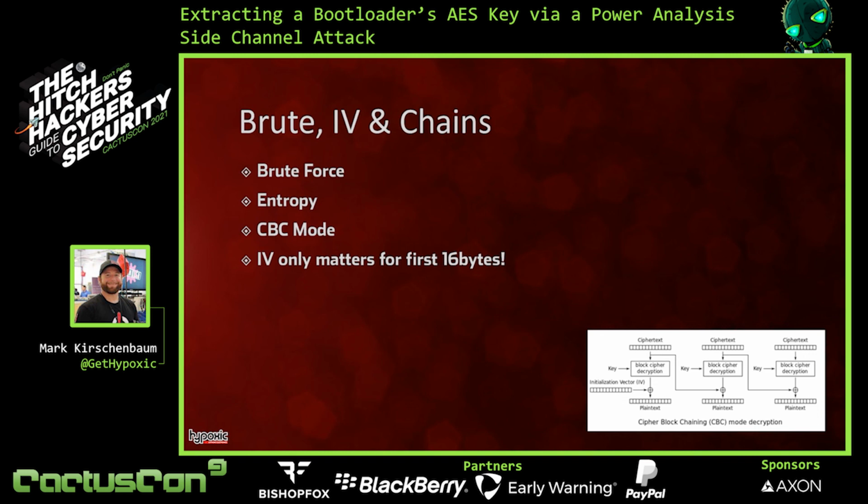But if you have an IV of anything else, you can go ahead and do a little bit of side-channel attack there. And there's ways around that. And for most of these, let's say for the Cortex or any of these parts, a lot of times it's just an interrupt table, and we could figure that out on our own. So it's not as bad as it sounds, that initialization vector, and pretty easy to circumvent.